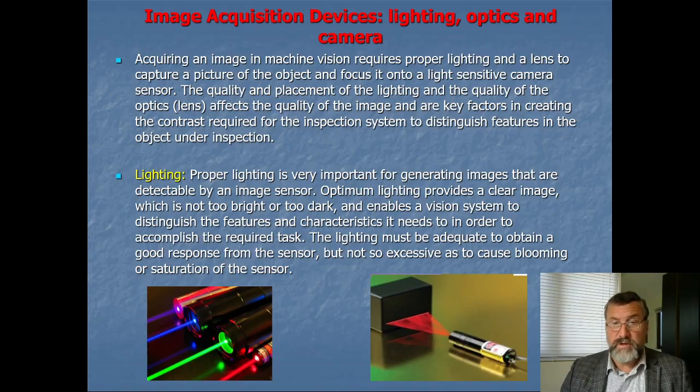And this is the sort of thing we use in the lab. I was just going through yesterday with a student, went through safety training, and he's going to be using a laser to measure some components. And so what we got here is a laser beam. Okay, you send it through a cylindrical lens, and it spreads it out into a plane of light, which is called a line generator. And the line generator is actually quite a complicated, quite a precisely made thing because it has to generate an even profile of intensities across this line, which is easier said than done. If you just had a pure circular cylindrical lens in there, it would produce a Gaussian profile, which would be brighter in the middle and dimmer at the edges.